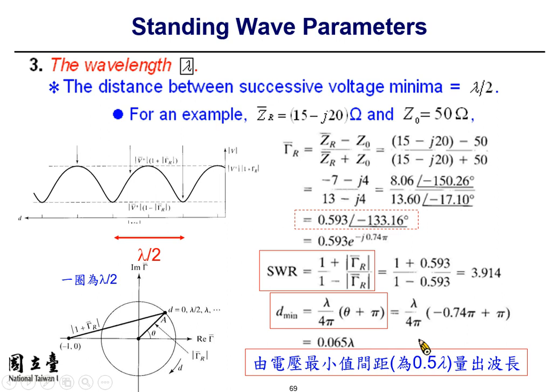So in the final, you need to know how to find this number using your calculator, okay? You need to do that. It will cost you about 15 or 20 points, okay? You need to know how to do that. And as you can see here, it involves some division of complex numbers. So you need to do the division by first changing them into polar form, okay? So the reflection coefficient can be found as 0.6, and the angle is minus 130 degrees.